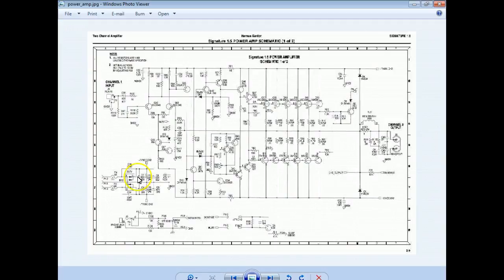It's using a center tap. So this would be a center tap coming in. So this would be a fuse on both sides. So this would have to run off the center tap transformer. This develops the positive power supply. This develops the negative power supply. It looks like 70 volts to me. So that means, though we couldn't quite get it, that would be almost 140 volts peak out.